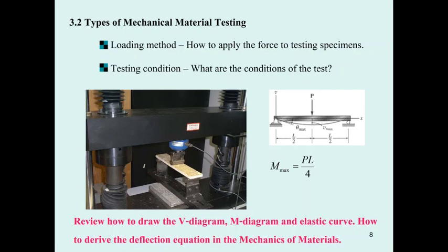You need to go back to statics. You have to draw the free body diagram, and then you can use the equations of equilibrium to find the reactions. And then if you draw the shear diagram and moment diagram, you may cut the beam to determine the Mmax, and the sigma max is going to be here, and Vmax is going to be in this equation. And again, go back to the first part of our discussion. You can see that the equation cannot be used if we don't know the modulus of elasticity of the beam.